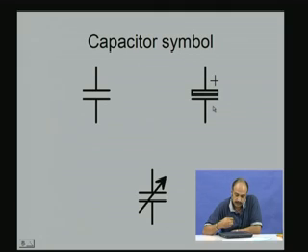And these are the symbols that you normally encounter in the literature, in electric circuits, for the capacitor. This is the most common symbol that you will encounter, two parallel lines with two leads coming out. And this is another symbol which is normally used for electrolytic capacitance, one with a thicker rectangular box type terminal, and another terminal which is a line. The box type has a plus there indicating that it is a polarized capacitor, that has to be always positive with respect to the other terminal. And then you can also have variable capacitors with the arrow indicating that it is a variable capacitor.